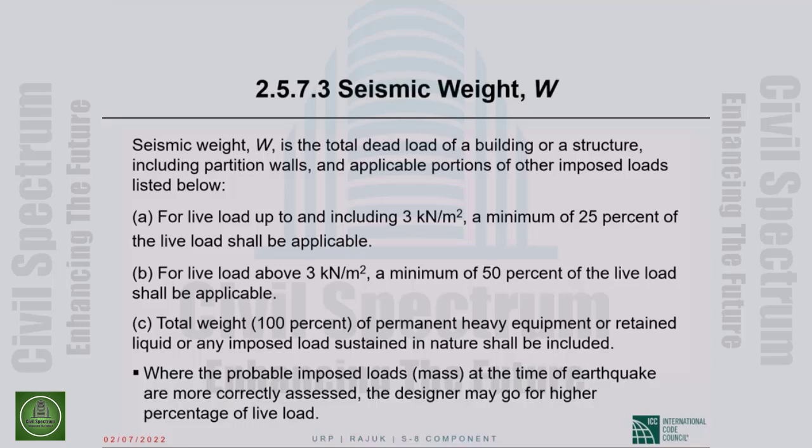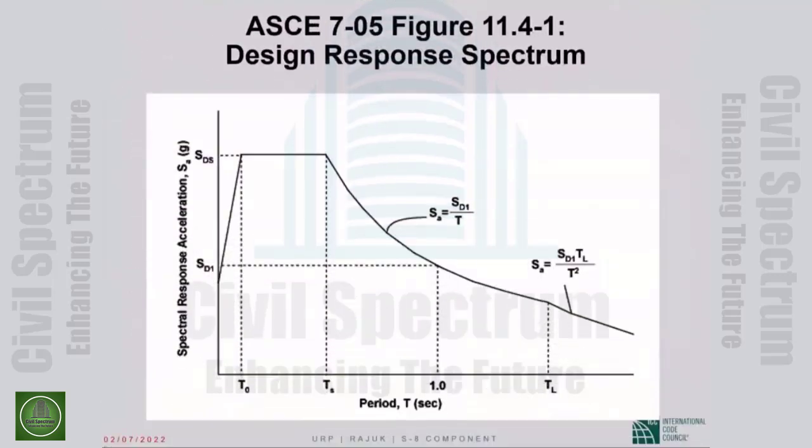So I don't know. There is a significant preoccupation with live loads that I do not understand. As you saw, ASCE 7, we include 25% of the live load for storage facilities, and that's it. Okay. Here it is 25% of everything, 50% of all occupancies with more than 60 pounds per square foot. And then it says you will do even higher. Yeah, anyhow.